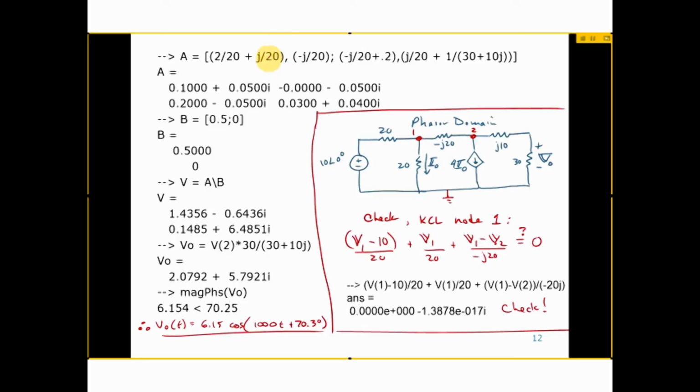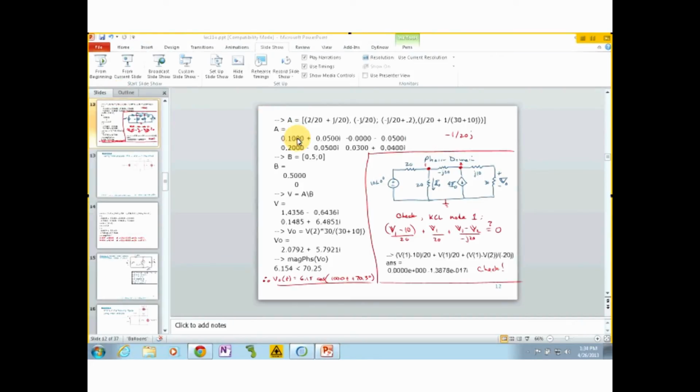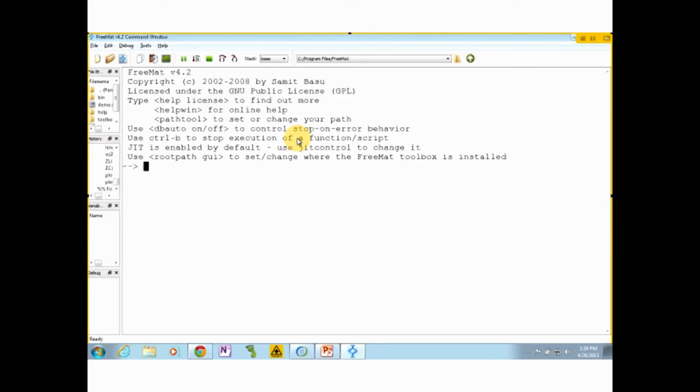But you're going to have to use parentheses if that j is in the denominator. Otherwise, if you just write minus 1 divided by 20j, it's going to be 0.05j. The j comes back up on top, unless you put it in parentheses so it's in the denominator. In other words, if you type minus 1/20j, this is something you have to be worried about, because of the order of operations. I'm never quite sure about this, so I'm usually cautious and I put parentheses around it to make sure that j stays in the denominator. I know on my calculator, if I just wrote 1 divided by 20j, the j would be on top. It would be 1/20th of a j.